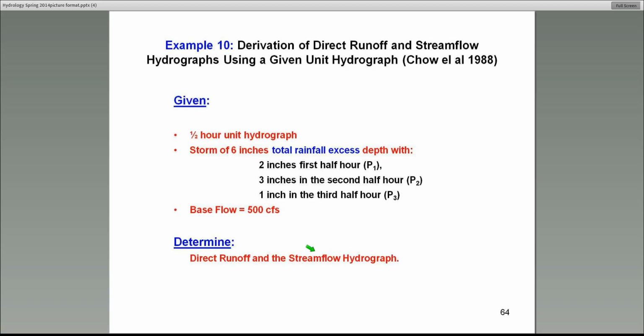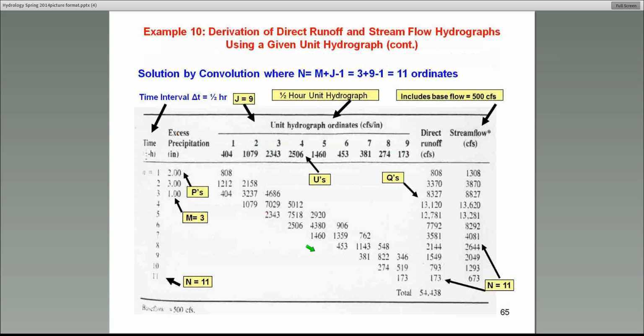They specify. All right. So to get the direct runoff hydrograph using the unit hydrograph methodology, here's what I would do. I would set up a simple table like this. It looks a little messy, but it's very quick to do once you set it up. In the first column is the time period. Remember, every half an hour. So 1 to 2 is a half-hour time interval.